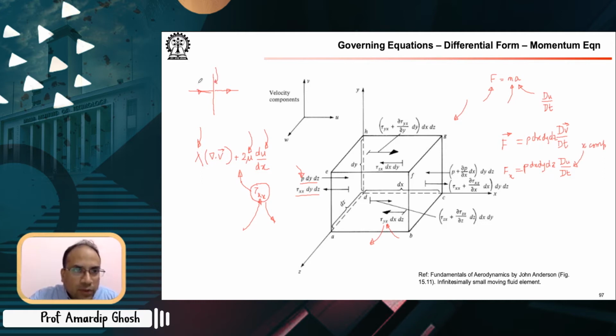What happens is, in the shock wave, the velocity of this flow decreases rapidly. So flow here could be at much higher speeds than the flow on this side, because the density increases. Conservation of mass requires the velocity to reduce after the shock wave. So there is a very rapid decrement in velocity as the flow goes from the left pre-shock to the post-shock state. In problems like this, your du dx can become significant, and hence your tau xx and terms like that can become important in the problem.